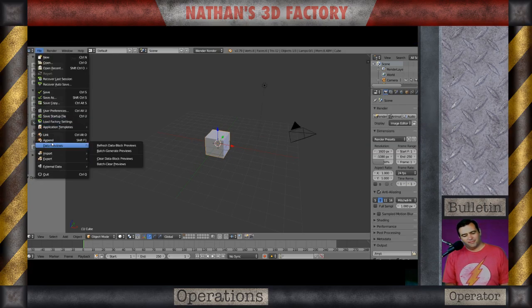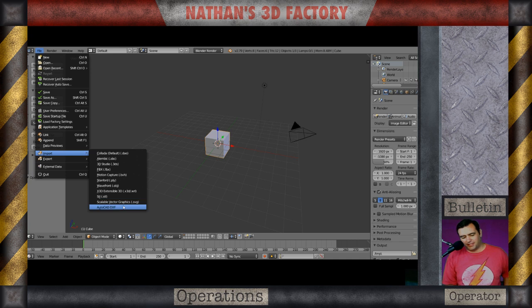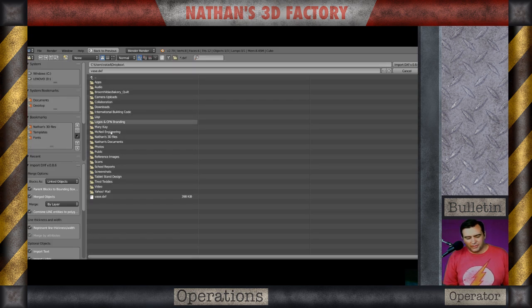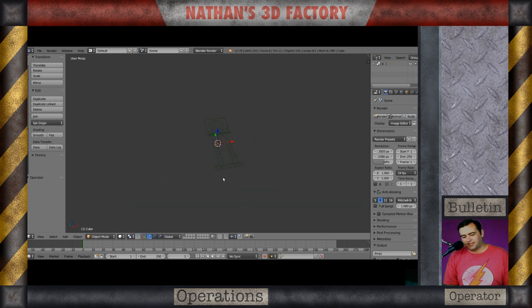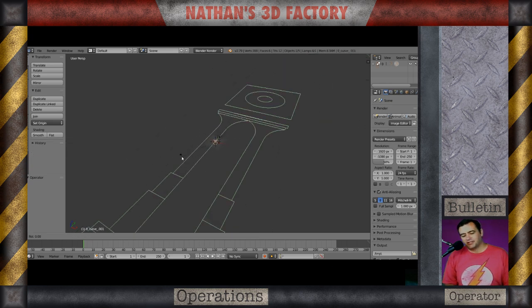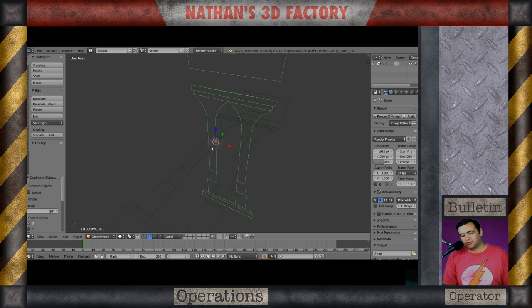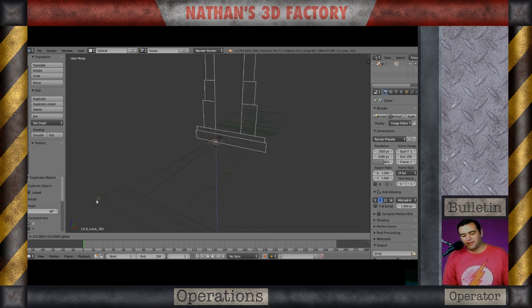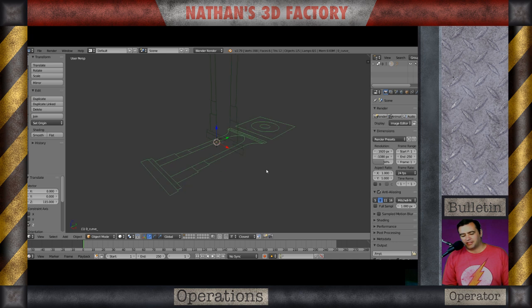Alright, we're in the default Blender scene, and what we're going to be doing is putting in a DXF object here. So I created this drawing in AutoCAD and then brought it into Blender. So now we have this nice object where we have a template for us to work off of. So I'm rotating this object 90 degrees about the x-axis first of all. And then I'm going to move it, transfer the origin, do all that stuff.